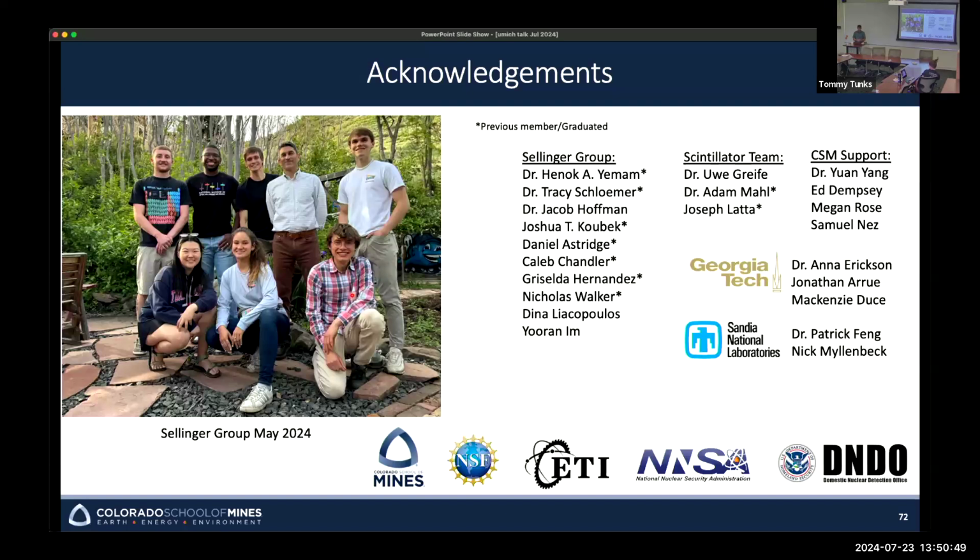Green is the easiest dopant to make. From a chemistry standpoint, it's easy, and it's also lower energy. A blue emitting material, especially in that deeper blue, starts to stress out the molecule quite a bit. In an OLED, the light you need to see puts a lot of stress on the molecule, and if it's emitting blue, that's stressing out the bonds. So there's differential aging in an OLED: the blue pixels usually die out faster because it's higher energy. So green is just perfect, and your eye is actually most sensitive to green. Yeah, that's kind of it, but I hope silicon photodiodes take over PMTs, because I think that would be a really neat avenue to explore.